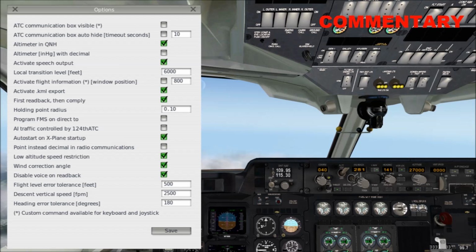When taxiing to the assigned runway, the plugin needs to detect when you have reached the holding point. This value has the unit nautical miles. For airports where the holding point is far away from the starting point of the runway, this value has to be increased. For example, if you taxi to the holding point and never get handed over to tower, you need to increase that value.